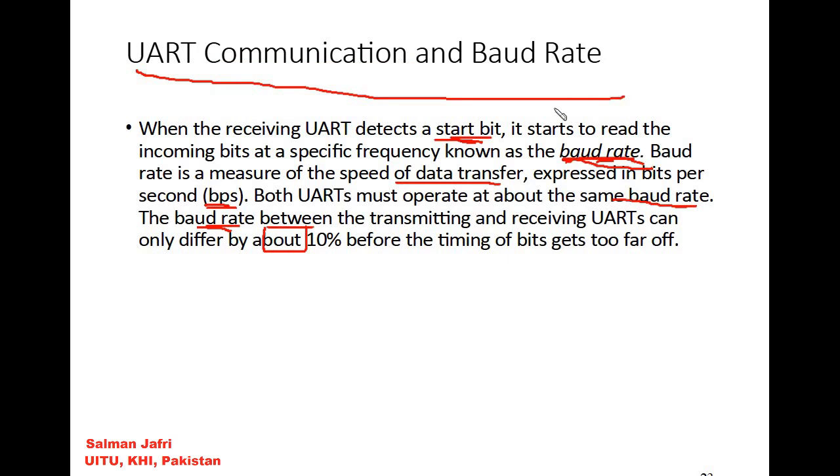So some points about the baud rate. When the receiving UART detects a start bit, it starts to read the incoming bits at a specified frequency. So the receiver's frequency is basically the frequency at which the receiver is reading, and this is called the baud rate. So baud rate is a measure of the speed of data transfer. It is expressed in bits per second.